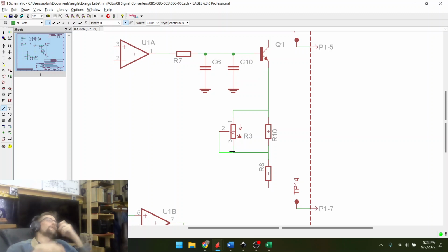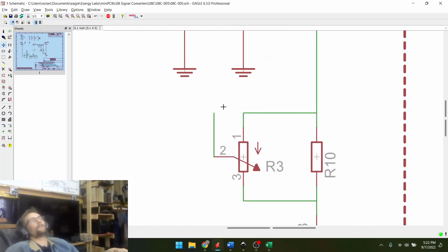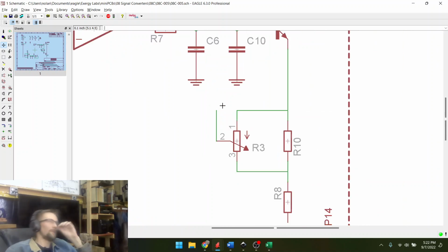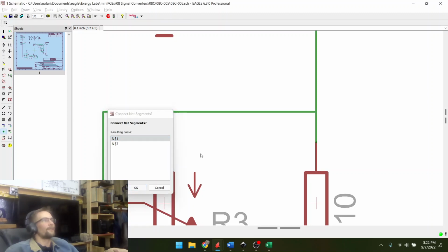Clockwise is going to take it toward 3. That would increase the resistance. Increasing the resistance, you're going to get more voltage drop for the same given current. It's going to reduce the current. So that would reduce the current. Whereas if I put it toward the top, taking it down there is going to decrease the resistance. So we would get less voltage drop per current, so the current would have to go up. So yeah, sorry about that. Should have said yes. I agree.